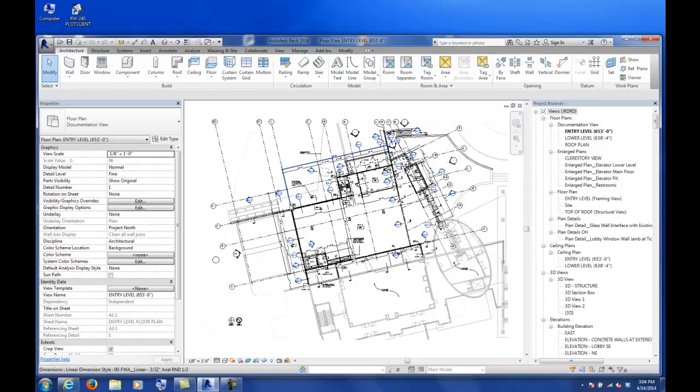So it depends. One method for getting around that is you could do a bunch of work, let's say editing a wall section or setting up views. You can always copy and paste those into the central file once you bring it back if you lose the connection. You could also bring it back and try to hit Sync to Central, and it might work. I can't guarantee it, because we've run into issues in the office where it says this file no longer talks to that central file, and you lose that connection. So you run that risk during that time.